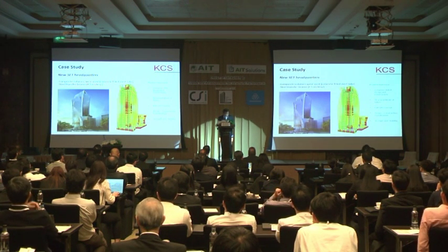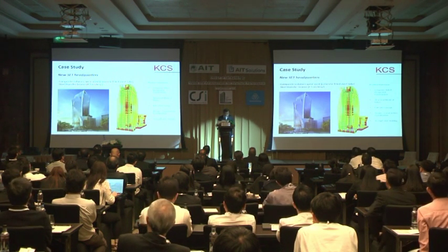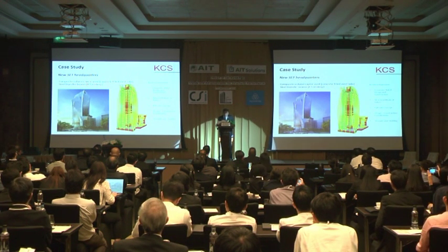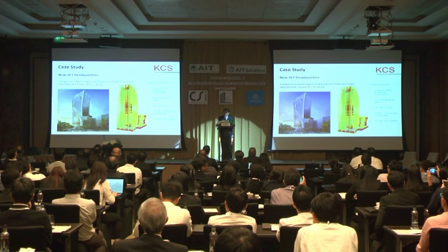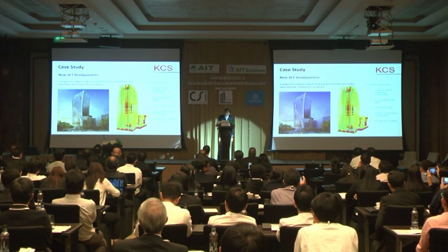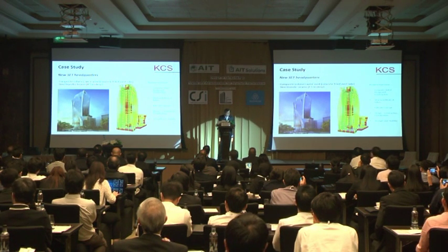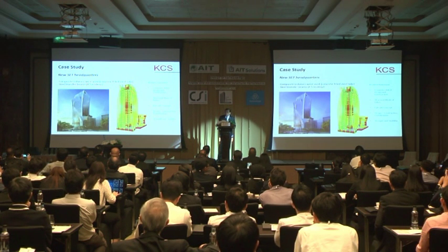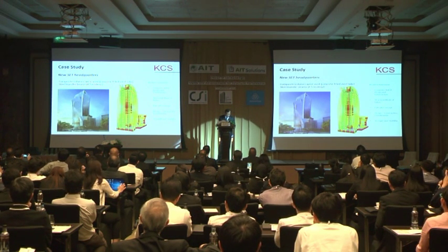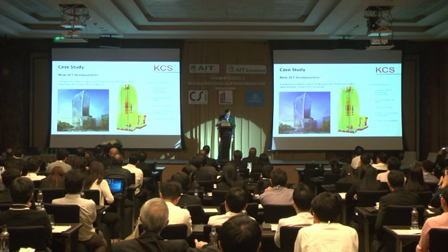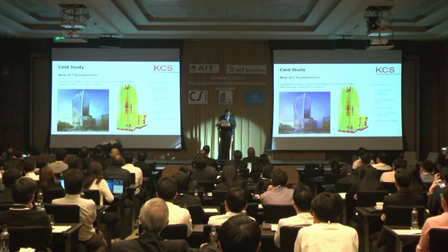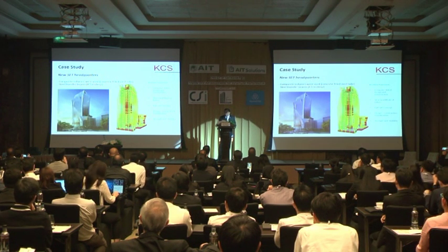The first example is the new Stock Exchange of Thailand headquarters on Ratchadaphisek Road. The building has curved columns, so computer-aided design and construction was required, and a potential mode of failure could be snap buckling of those curved columns.